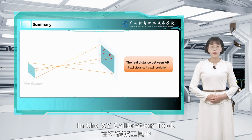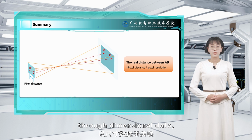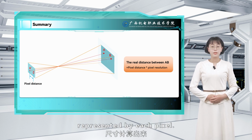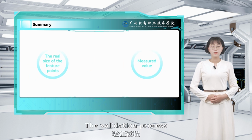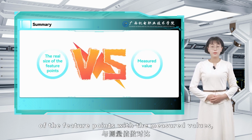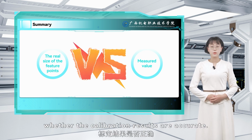In the XY calibration tool, the pixel distances in the image are linked with actual distances through dimensional data, enabling the calculation of the real-world physical size represented by each pixel. The validation process involves comparing the real size of the feature points with the measured values in order to verify whether the calibration results are accurate.